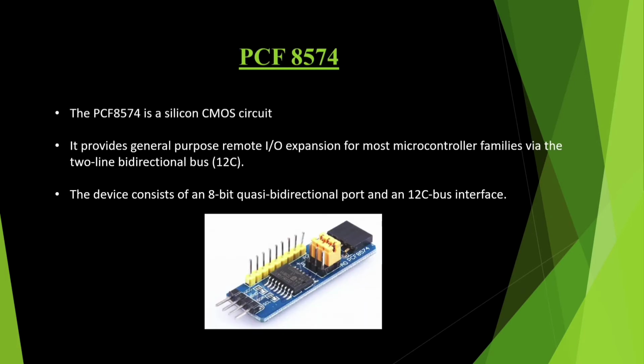Now let's see what the PCF8574 is. It is a silicon CMOS circuit. The device consists of an 8-bit quasi-bidirectional port and an I2C bus interface. It provides general purpose remote input-output expansion for most microcontroller families via the two-line bidirectional bus.